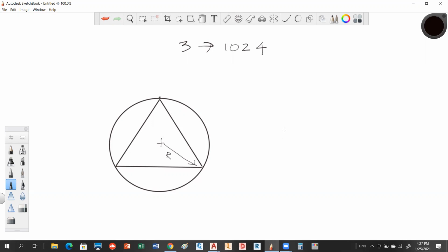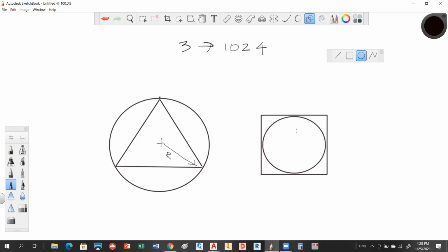The other one they have is what's called a circumscribed polygon. So if this is your polygon, I'm going to try to draw this as best I can. This is going to be hard. Let me see if I can do it this way. You get an imaginary circle inside of this polygon. The circle's imaginary. You will define the center of your polygon, and you'll define again the radius. The radius in this case goes to a tangent point, and that's actually the midpoint of that distance.